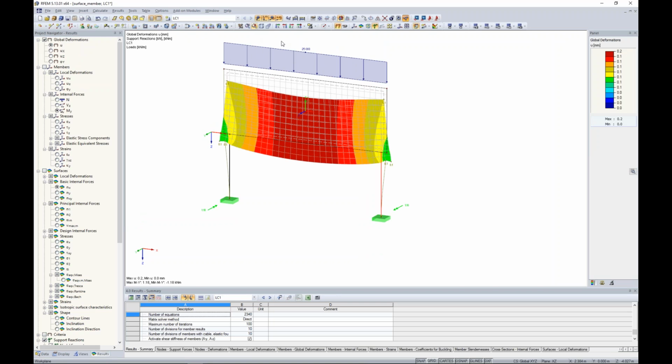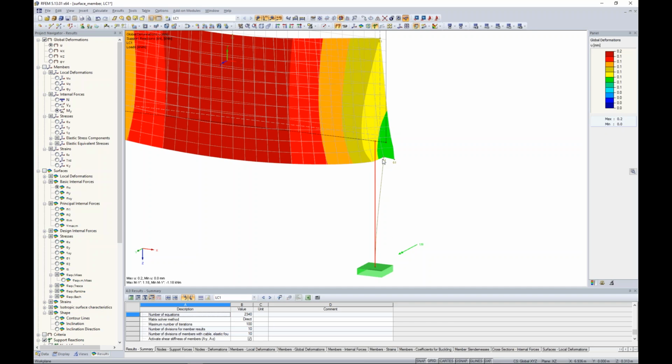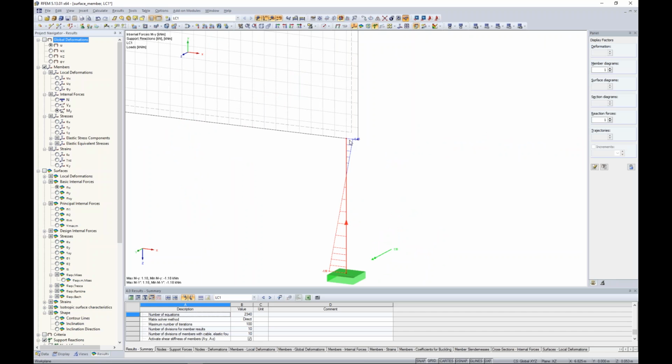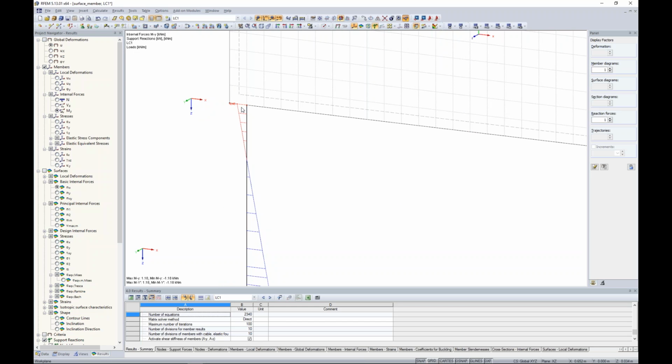So already in the deformations, you can see that there's like a corner, and also in the bending moments of the column, it's not a real frame bending moment, it's quite too small. And the reason for that is that the shear panel has 3 degrees of freedom, translational deformations, but the column also has a rotational degree of freedom. And this is an incompatible FE mesh in this node. And we have to think how to connect the column with a rigid connection to the shear panel.